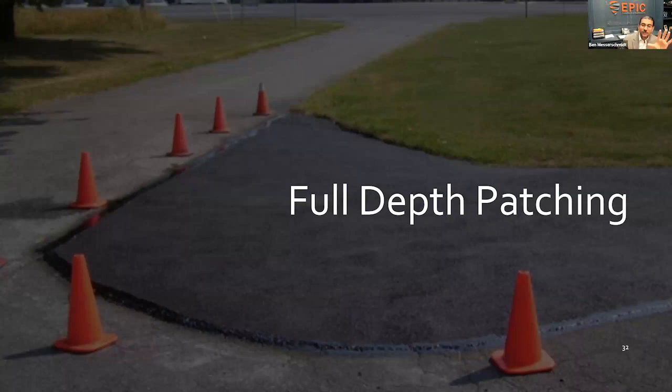Now, patching versus completely redoing it with a mill and overlay with some structural based repairs along the way, those are likely going to be your two options at that point. Mill and overlay, just so everyone's aware, is essentially large scale machines chewing up the actual roadway surface, usually to a depth of about 2 inches, and applying a brand new asphalt coat on top of that.